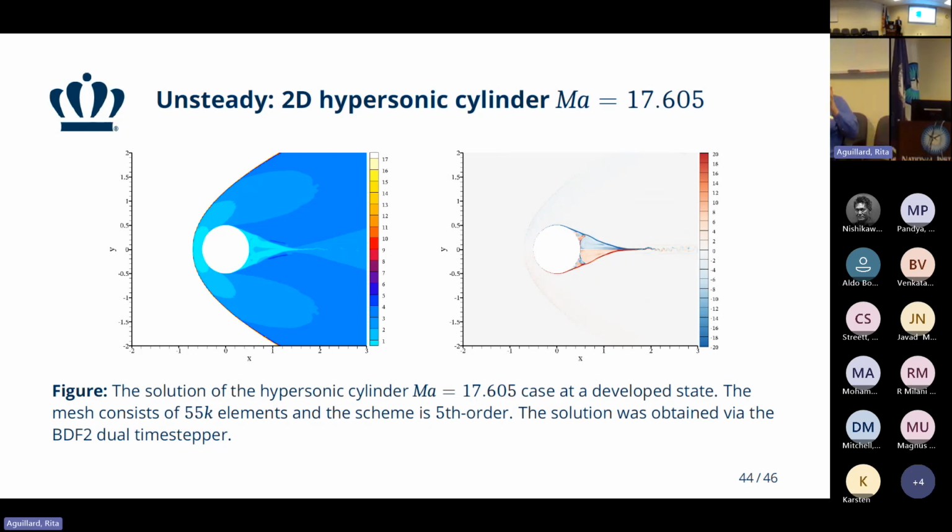So it's basically an O-grid? Pretty much an O-grid, but we don't really resolve everything. There is also a wake region, and there is a high resolution in the wake region. Yeah, so in this region it's higher. And it's fully unstructured. And what type of cells again? Hex. Yeah, this is 2D, so quadrilaterals. Quads, yeah. We only do quads. And the Reynolds number here is around 400,000. So it's very high.